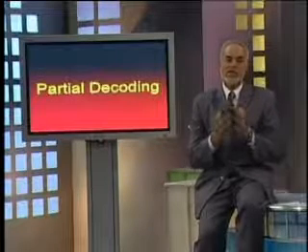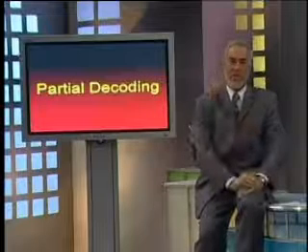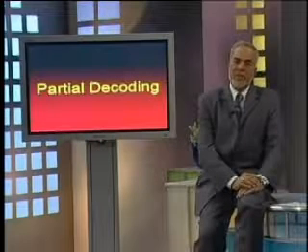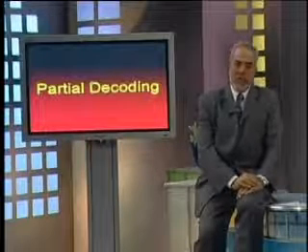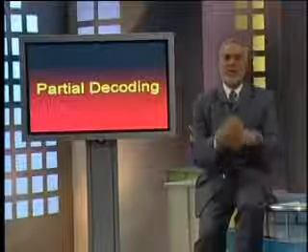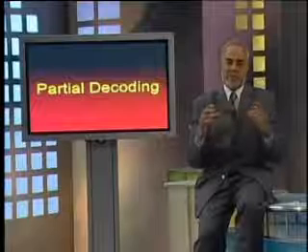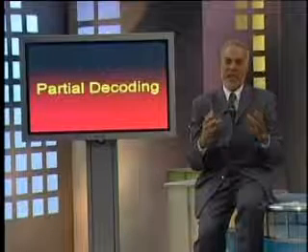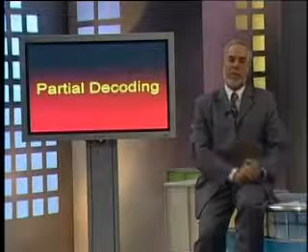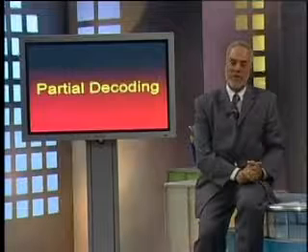As an example, let us say we have 4 registers, and each one is 16-bit wide. Now, the addressability is only 1 byte. So therefore, for each register, we need to have 2 addresses for IO interface. So let us say we have the first register as a data in register. As an example, we could indicate the addresses as 56 and 57.